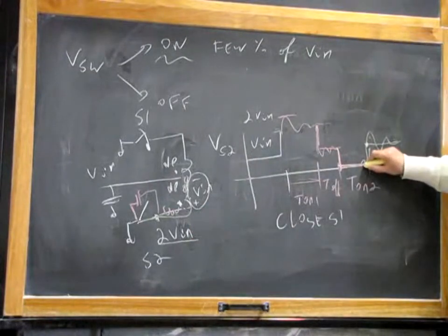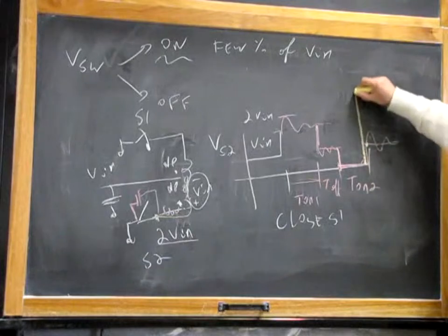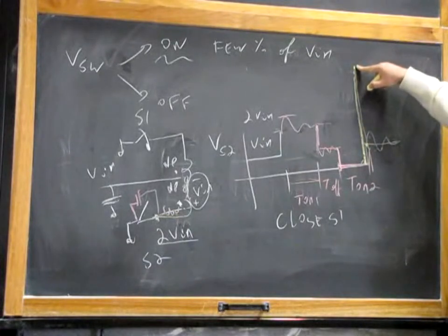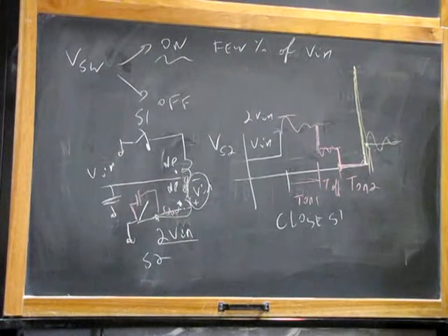And you can have a very narrow pulse, 50 nanoseconds, something like this, but it goes up, up, up, up. And guess what happens right here? Boom. Boom, boom, kaboom, depends on what language you speak. This happens every time you are opening an inductance with the switching series and you don't provide a circulation path for this.